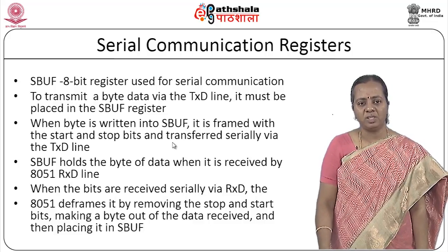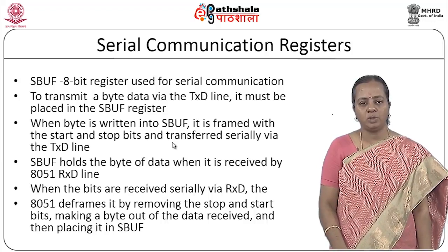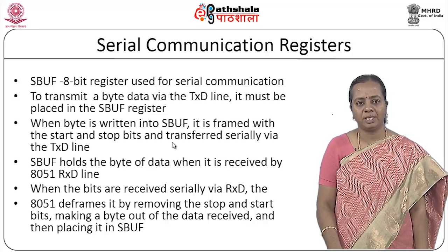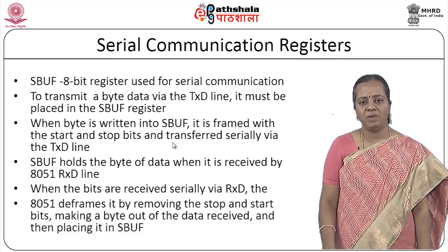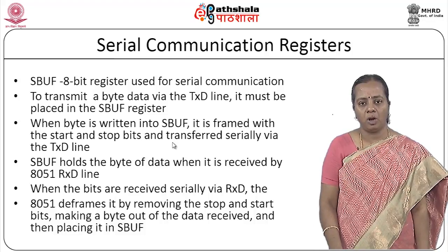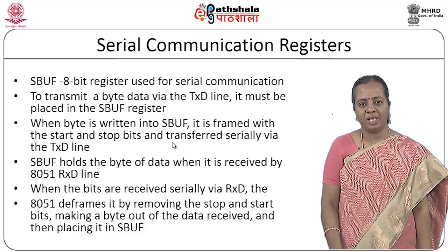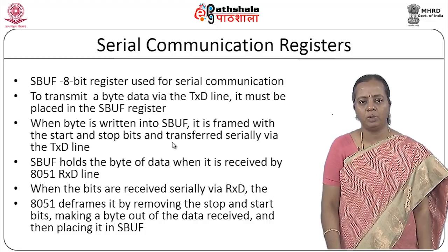So when you want to send it bitwise, it has to be placed in one place so that it gets serialized and sent. In the same way, when I am receiving bit after bit, I need a place where I can store all these 8 bits. After that I will concatenate them and make a single word, then I can give it to the 8051.